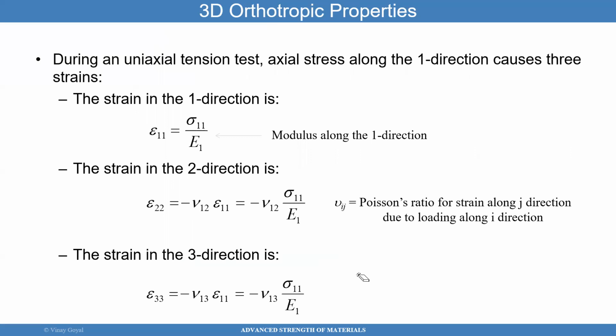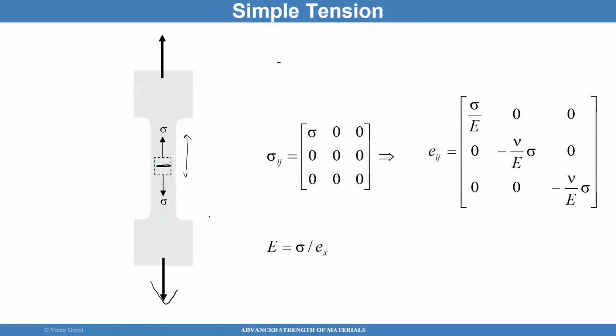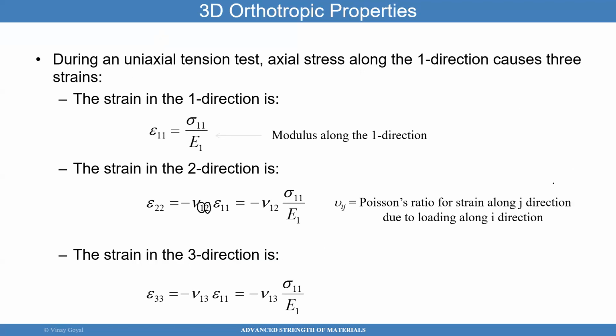So let's do an example with composite materials, just because composites are used quite a bit, so you can learn how this is done. So I apply a load sigma 1 in the test, and I get this modulus. I can measure that using a test just like this, okay? And then I can measure the Poisson ratio. And the Poisson ratio is going to be load applied in the one direction, measuring the contraction in the second direction. That's what the two indices mean. Now, earlier, I didn't use indices because these were isotropic materials, but for composites, the Poisson ratio can change depending upon how you test. And so I'm going to track that now.